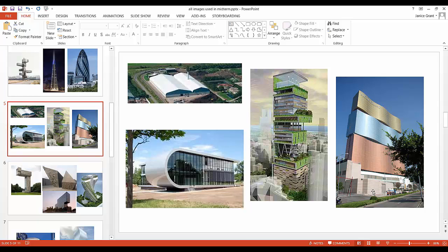Same thing with this one here. You may have 4 different levels, and on each one of the 4 levels you have a different set of lines that makes this 2D geometry, and then use create form to create those forms that are on different reference planes. So you can see that a lot of these are profiles that are either on a vertical reference plane or horizontal. This one, for example, is a profile that's extruded, or we're creating using create form.